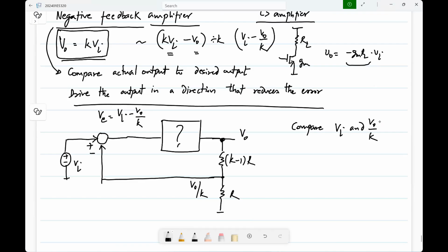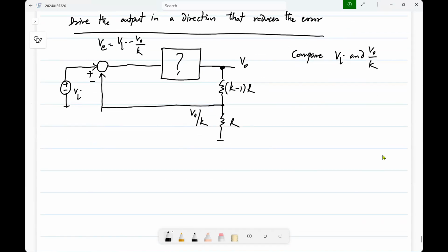So again, the easiest thing to imagine is that the feedback is not there. Again, in the driving analogy, what happens if the feedback is not there? First of all, let's say this is 0. So you're getting a constant input. Similarly, you can imagine driving with a stuck speedometer. The speedometer is stuck to some value, and you have, let's say, no other perception of speed. Not a good way to drive, but anyway, for the sake of this analogy, it's fine. So then what will you do if the speedometer is stuck at 20 and you want to go at 40?